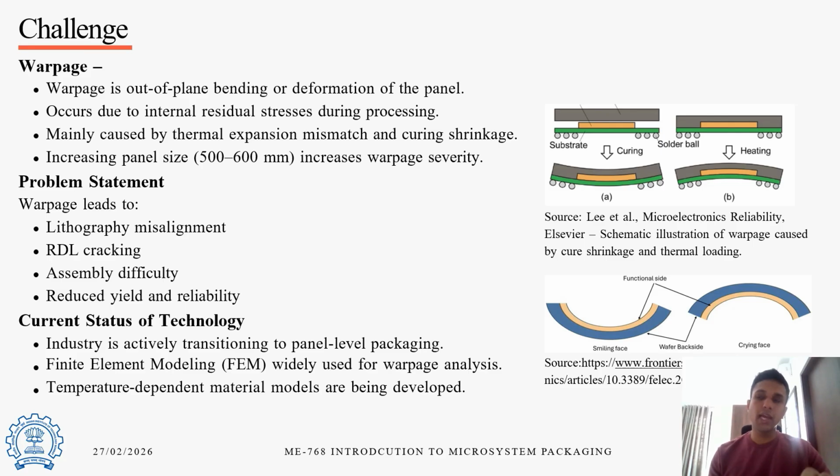To study the warpage, we have analytical and computational methods. The major issue with the analytical method, which is the only available one, the Timoshenko multilayer method, is that it considers the lateral area to be the same. In our case, the lateral area is not the same at all. It varies from layer to layer. The area of the chip is not the same as the RDL layer, which is not the same as the epoxy compound. Also, the variation of parameters with temperature cannot be considered in the analytical model. That's where our finite element models, or the computational models, come into play.